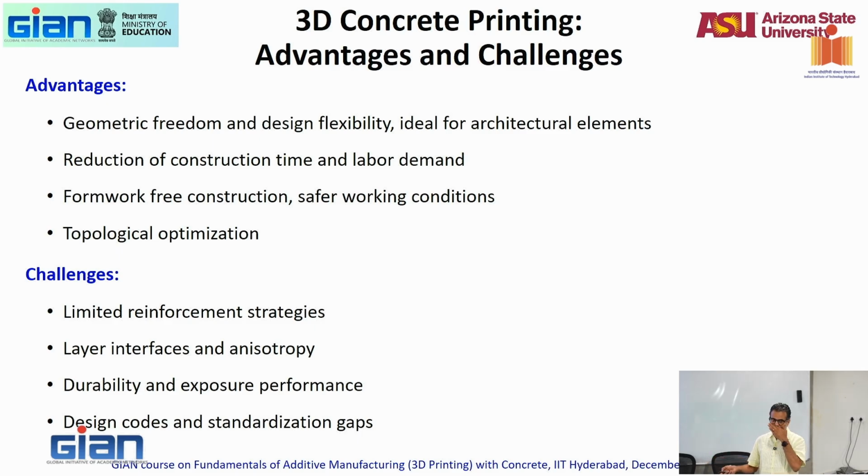Durability and exposure performance. There is no reason why 3D printed concrete will be less durable. Of course, there are more layers, right? So if the layer interfaces are not good, you will have problems. But if you control the interface, there's no reason it will be different in terms of durability. So again, you need to do tests, you need to understand them, but it's not an insurmountable problem. But again, some people use that as a challenge.